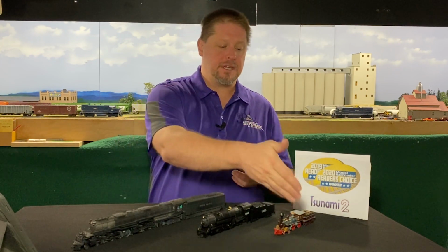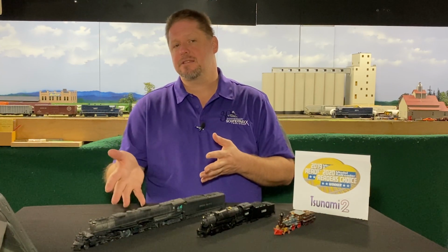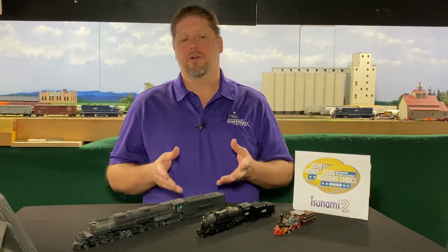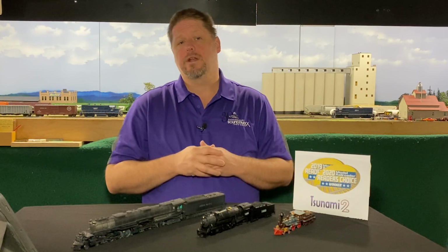So for example, these two locomotives are what's called a conventional rod locomotive, which means they have 2 cylinders and you get that 4 chuffs per revolution. As the piston moves back and forth, you get 1, 2, 3, 4 chuffs per revolution. Now in the case of a heavy articulated, and this is the simple type of articulated, you would actually get 8 chuffs per revolution of the wheel because you have 2 sets of cylinders, one in the front, one in the rear. You can also select a 3-cylinder type locomotive in CV112. So again, you have this choice.